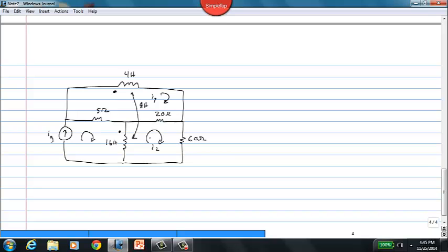So what we need to do now is apply KVL and KCL to write the equations that govern these. So let's start at the top one, the mesh containing I1. If we analyze I1, it's going to enter voltage polarities such as shown there. So what we would say is I1 times j omega times 4 Henrys plus I1 minus I2.